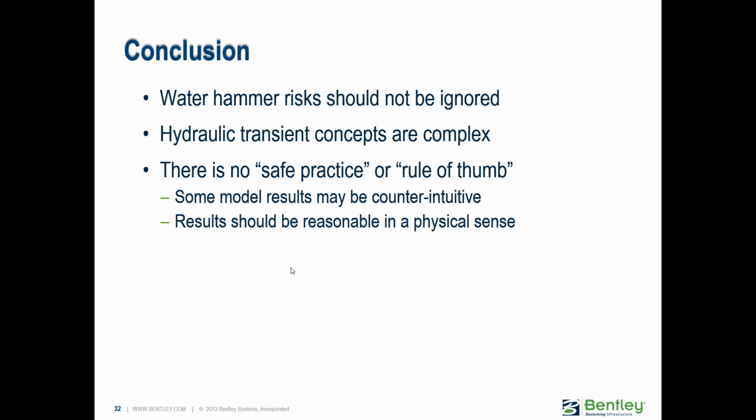Transient simulations can be complex. It's not like WaterCAD or WaterGEMS, where you just put in some basic information, and maybe you can simulate a connection to an existing system with a pump and a reservoir or something, and get the pressure results you need pretty quickly. With Hammer, because of how complex these things are, it's that much more important that things are modeled exactly the way they are, and that you've got accurate diameters and elevations. It's that much more important in Hammer, because things are so sensitive to that.